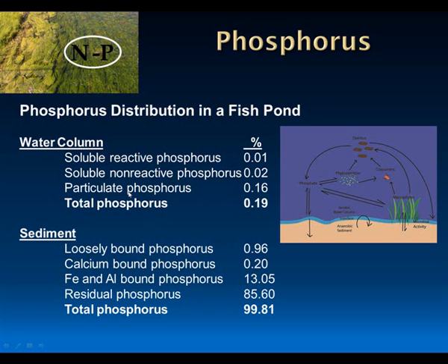It's associated with particulate in suspension. So phosphorus really likes to be bound to sediment. And that's why in the paper that we read on the turbidity measurements in the Utah watershed, in the Little Bear, turbidity and suspended sediments were a good surrogate for total phosphorus.